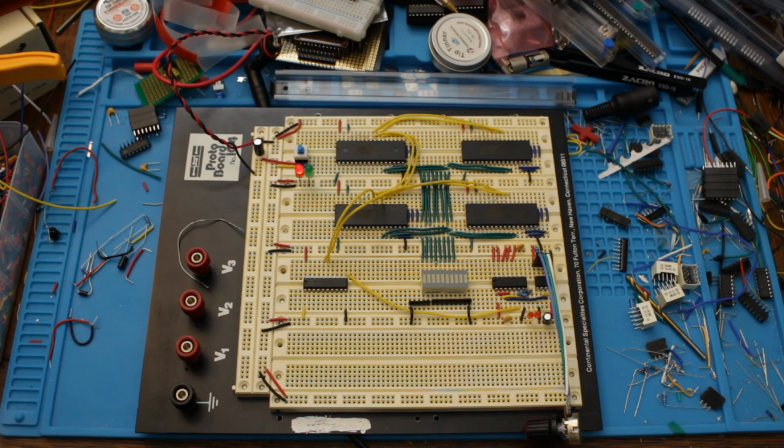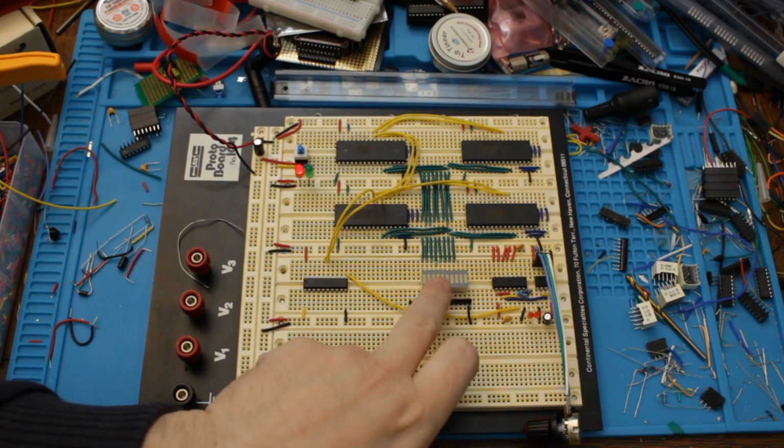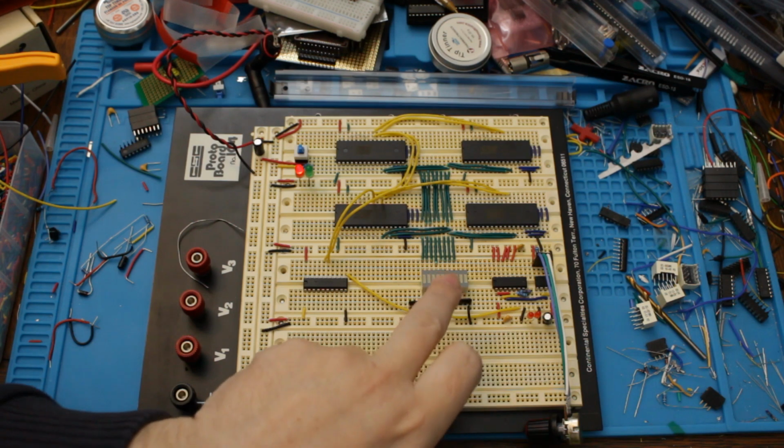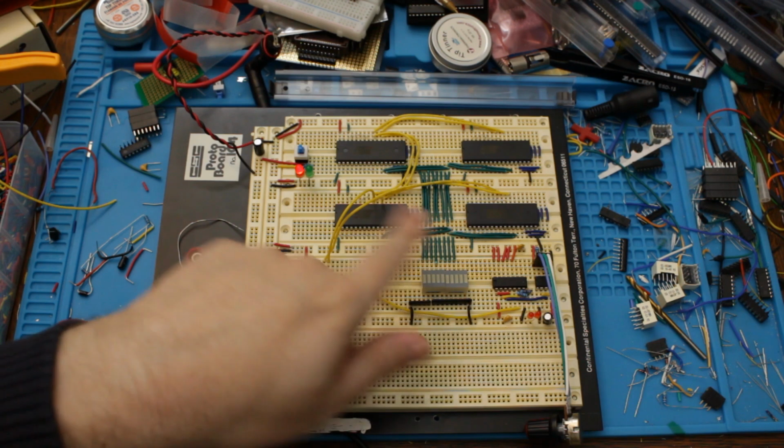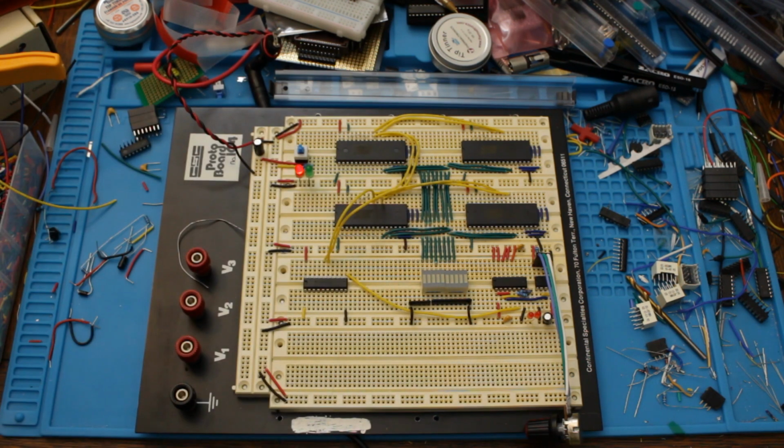And yeah, all of those 4-byte words for all addresses are going to look exactly the same, so we're just going to run the same instruction in this case. And the instruction I programmed in is a simple jump instruction that hopefully will allow us to see, via the visualization of the data bus and the address bus, whether the opcodes from the ROM are getting into the CPU and whether it's processing them properly. So it's a very simple test.